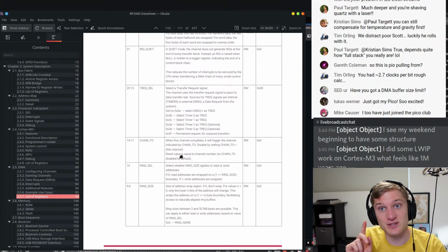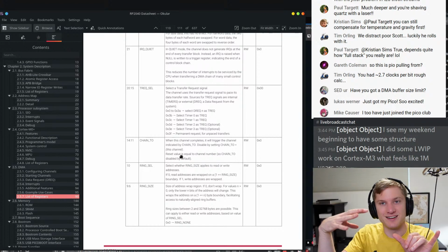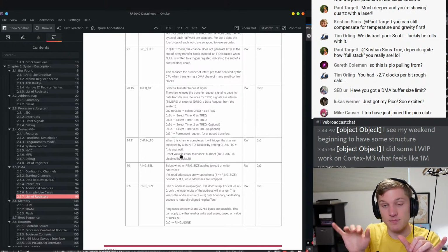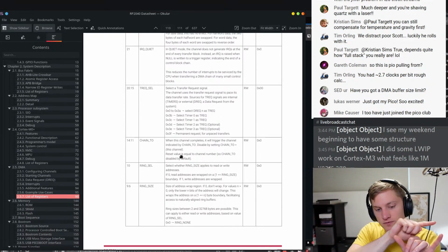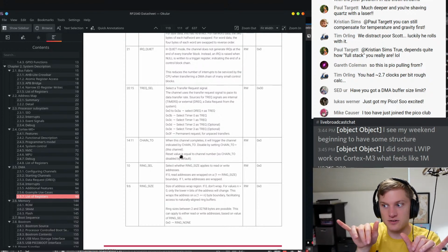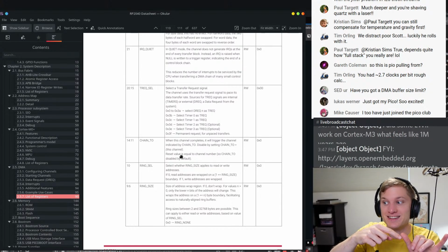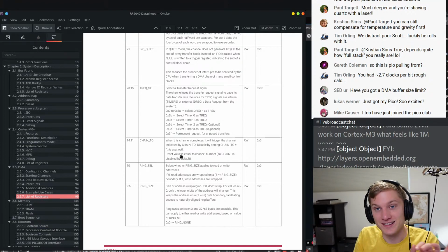The other thing that chain 2 can do, which I don't think I need here, is you can have chain 2 as almost a meta DMA. So instead of DMAing memory to peripheral, you finish your buffer, you trigger another DMA, and that DMA is actually writing to the DMA peripheral to change the buffer that the first channel DMAs to, changing the settings of that first thing.